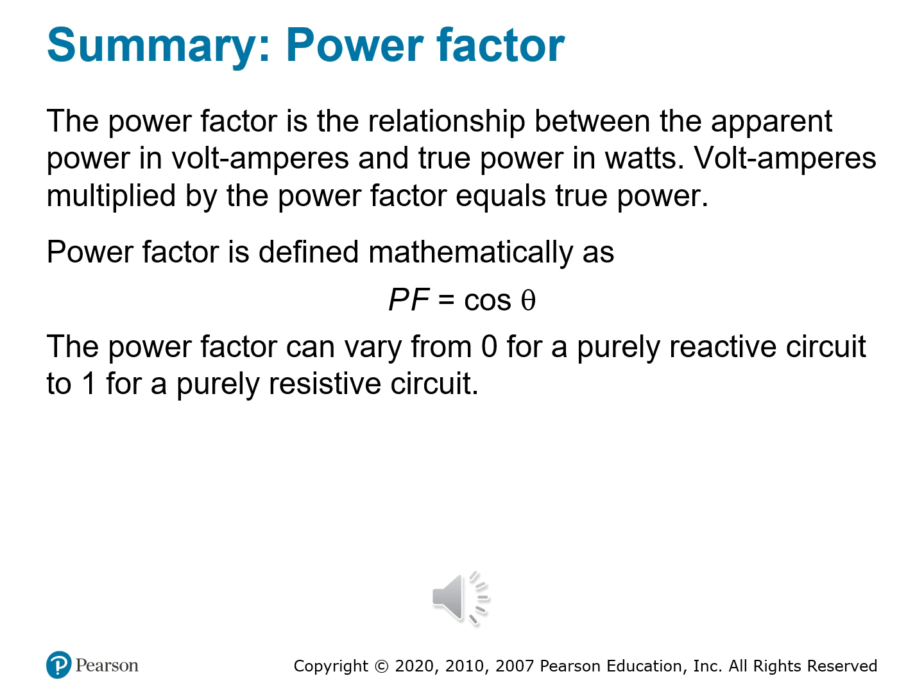And I said it similarly back then. I'm going to say it again. It's deceptively simple. The power factor, denoted by PF, is equal to cosine theta. And we derived how we got that the last time. And theta is that phase angle between the voltage and current. So that means that the power factor tells you how much of your apparent power is actually doing useful work and how much is just taking a reactive joyride through the circuit.